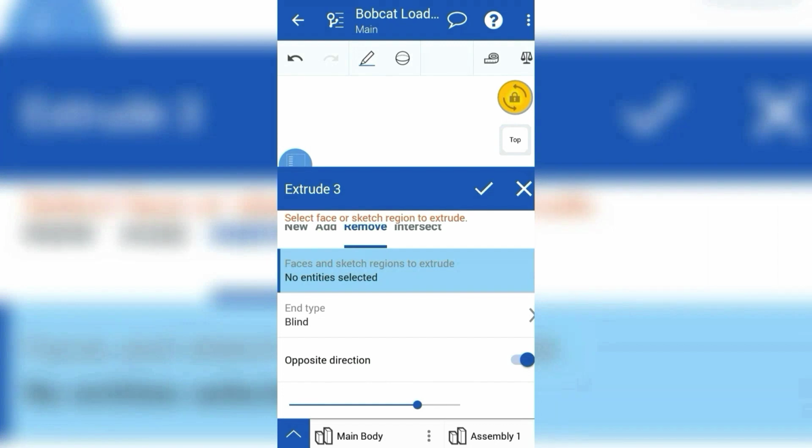Similar to the extrude of sketch number 2, here also choose Extrude Remove, but do not make it through all, just keep it blind. From the features, choose Extrude, switch to Extrude Remove, just keep it blind, and here we want to remove only 40 mm of the material.